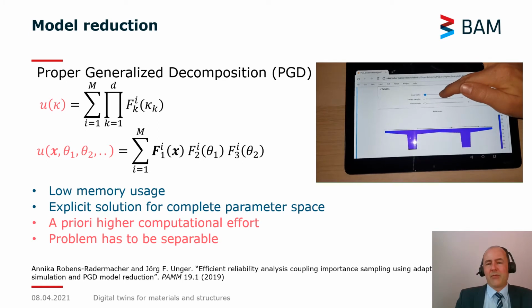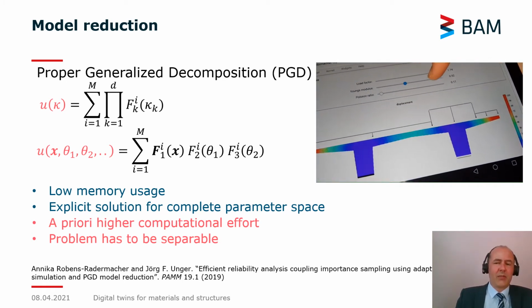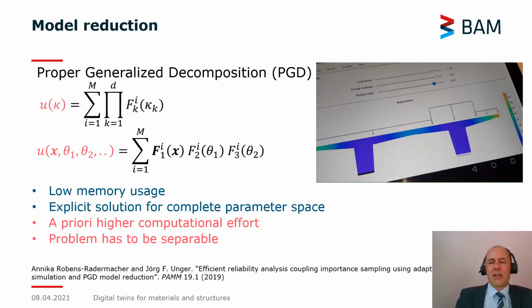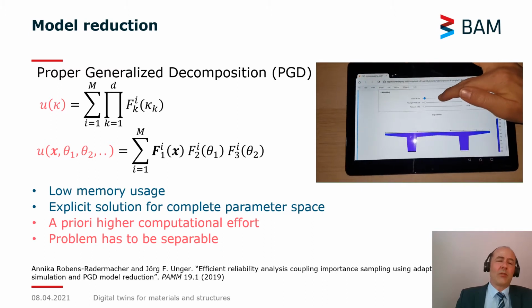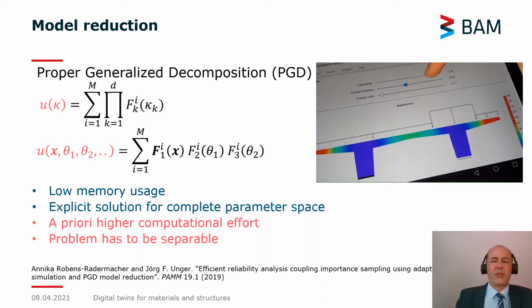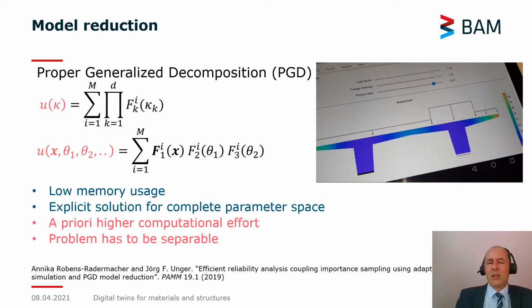So usually your displacement is the degrees of freedom in your finite element simulation. And then you're interested in, I don't know, an optimization where you would like to change the Young's modulus, Poisson's ratio, strength criteria, whatsoever. And then for each of those parameter configurations, you'd have to redo your computation.